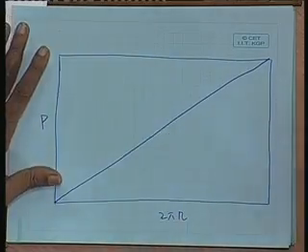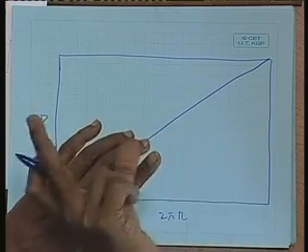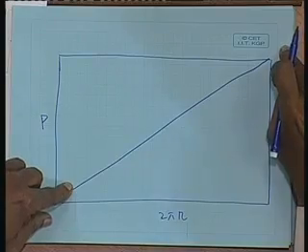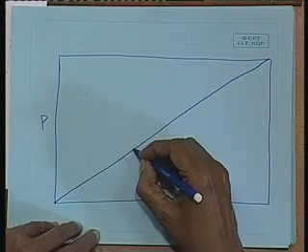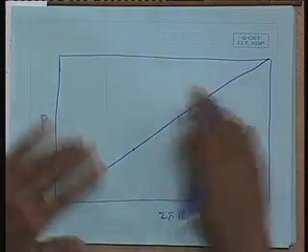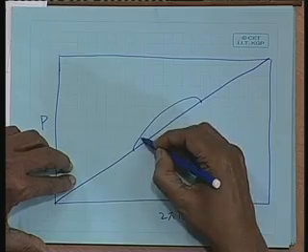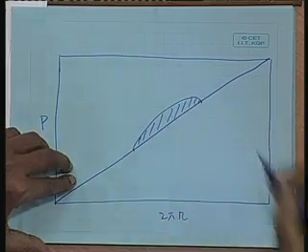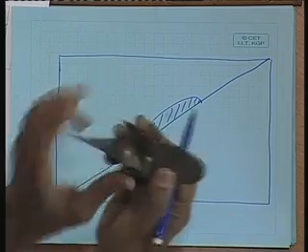Now, when I expanded the helix, since at a particular radius of the propeller blade, the face I am talking about is a part of the helix, that would come as a straight line here. Actually, it is not straight, but it will come as a straight line. So let us say the pitch was coming here, face was coming here. Now, I am not giving any offset to the face. Let us understand the geometry first. And it has a back like this. Let us say this is my blade section. Clear?